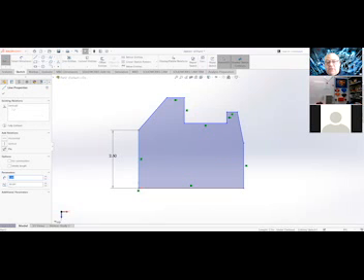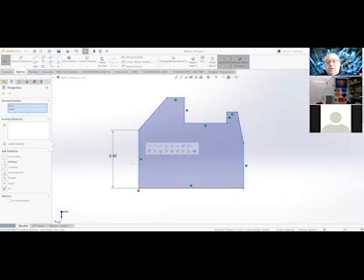So it's got vertical number 5 there. Go ahead and click on the other line on the other side. Now, are they both blue? No, but it switches to side that's vertical number 4. Now, if you hold your control key down and select the first one, now you have lines 1 and 9. So there are constraint numbers and there are element numbers. In this case, I've got line 1 and line 9.